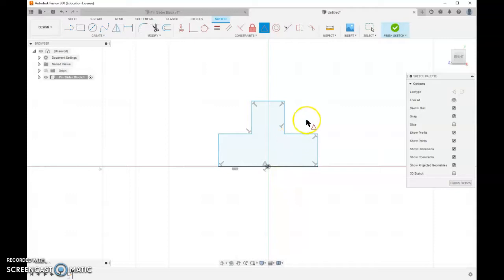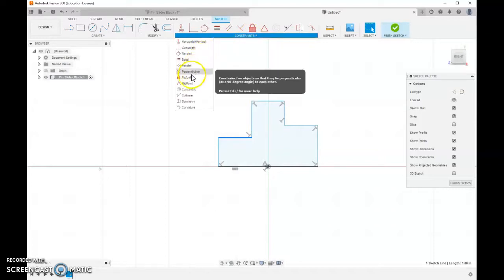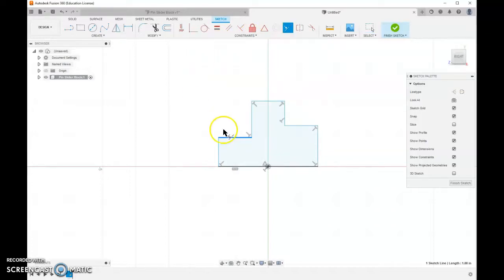Next thing is, and always have to hit OK, escape out of that tool, you see here I can move these lines up and down independently. So what I want the drawing to do is move both at the same time. The constraint I want to introduce is called collinear. I'm going to select that one, which is already selected, and then the second one. Now you can see, when I right click and hit OK, that when I move one, they both move at the same time.